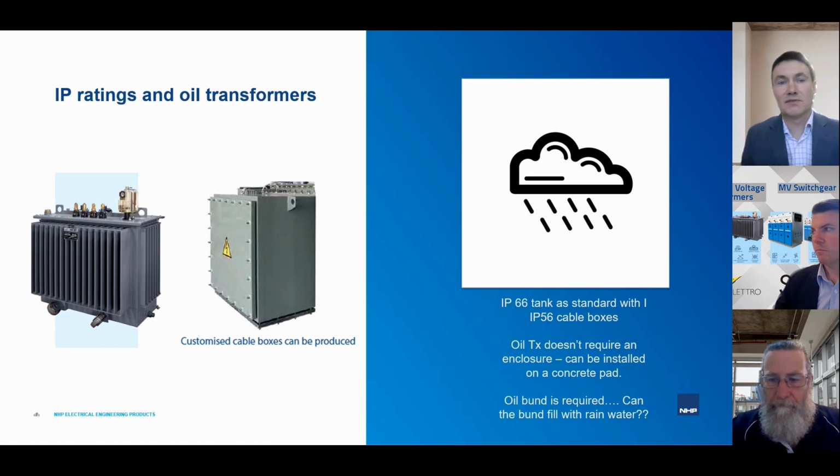There are two solutions we've seen in the industry. One of the solutions is that there are special filters available that you install in the outdoor bund that allow you to segregate between the oil and the rainwater. The solutions are there. We haven't used them ourselves. It's not all that easy because you still have to drain that rainwater. So it's quite a complex solution.